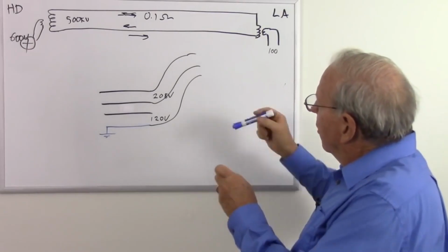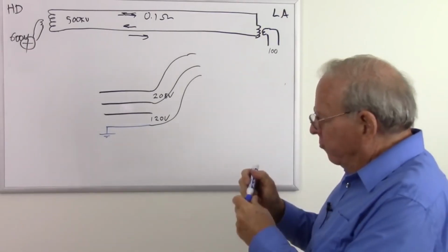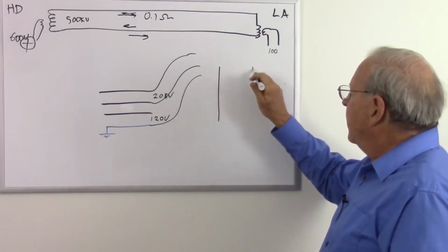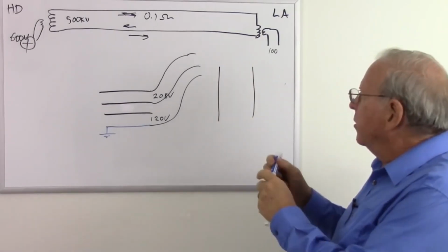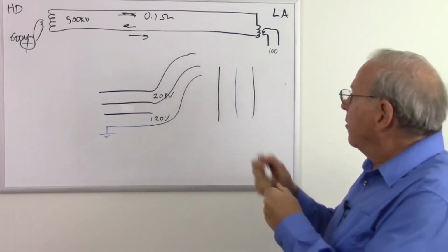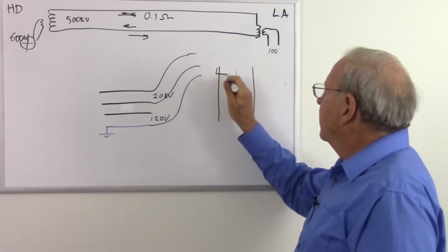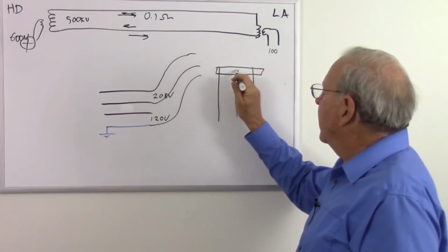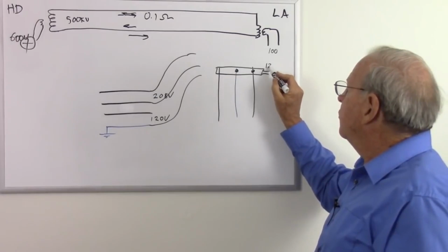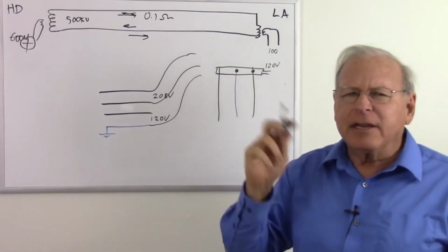And so your circuit breakers, let me draw the breaker box sort of here, will have one phase, another phase, and then the neutral in the middle. And we'll have circuit breakers that connect. There's a circuit breaker, but it only connects to the neutral and one phase. What does that give us? 120 volts. It might be a different voltage.